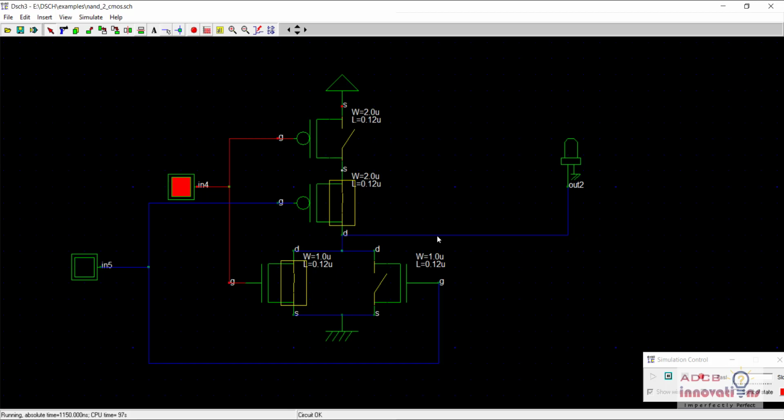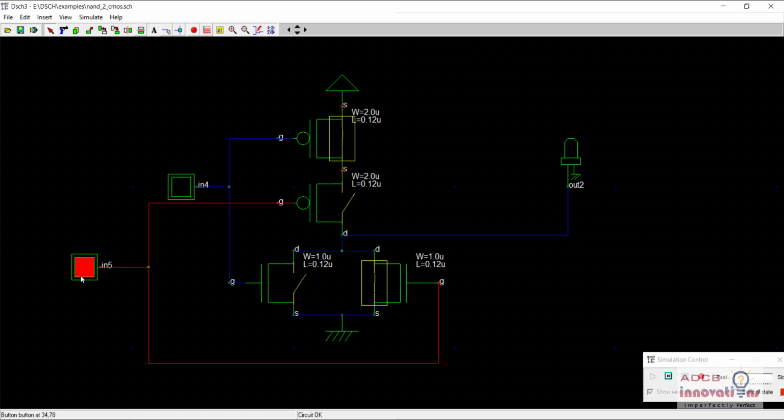Similarly, when the other input is 1 and the previous input is 0, this PMOS is open circuited, and thus logic 1 flows from here but didn't go past this point. Okay, thus we didn't get logic 1 as the output. However, in this case, since these NMOSes are parallel, no matter if this NMOS is open, the other NMOS is short circuited, and thus logic 0 flows from the source to this drain, and we get 0 as the output. Okay, so when both of them are 1,